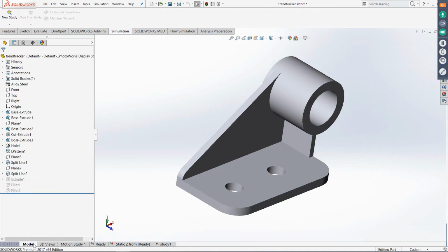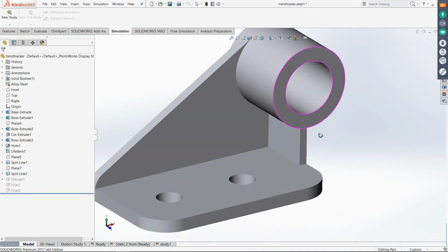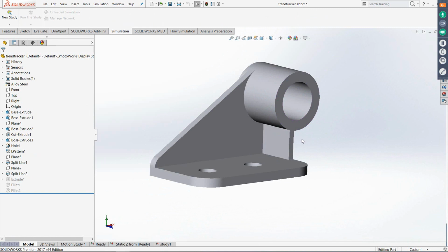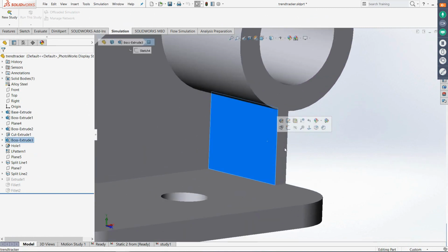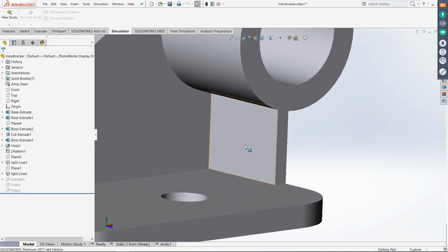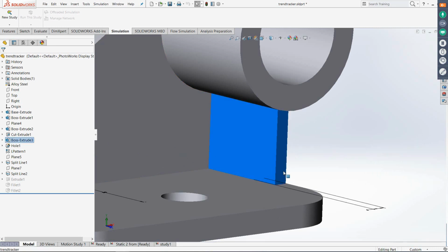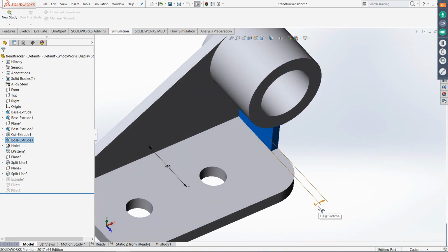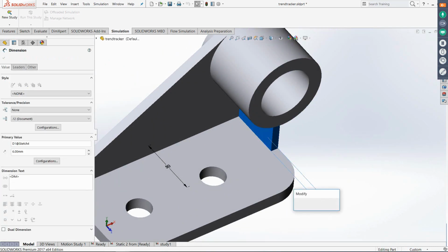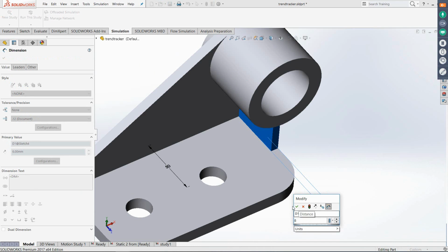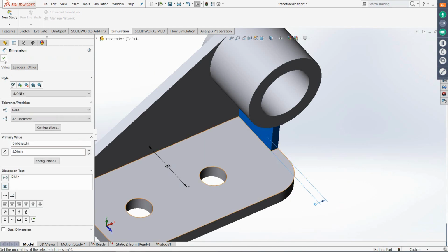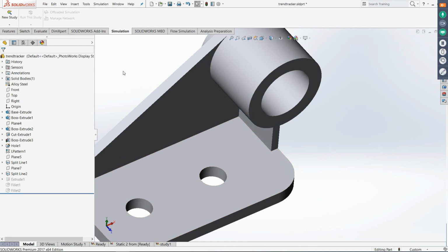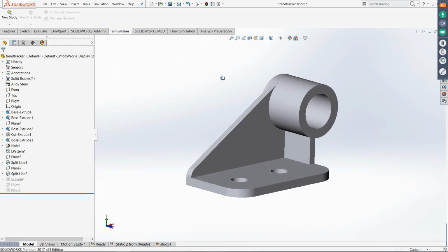So now there are many thoughts which can come into picture here. I get back to the CAD front end. I click on this particular feature either through the feature tree down here, or it could be as simple as double clicking on the feature. At the moment you can see it has a dimension of 6 units. I increase it to 8 units. Accept it. I rebuild this setup so that everything is updated well.